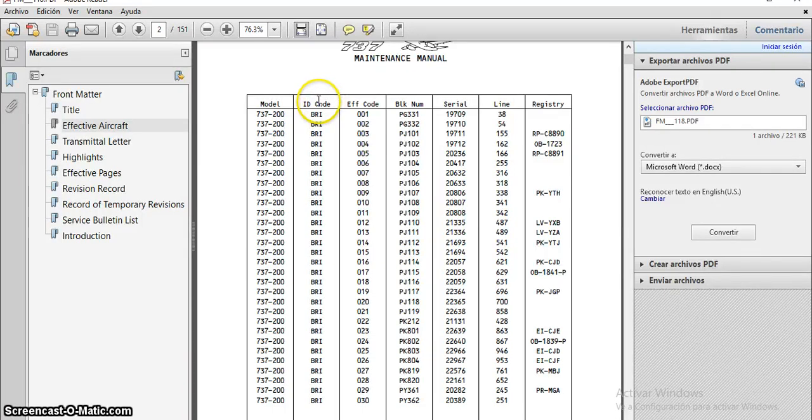Well, the next part of the laboratory is based on the steps and procedures to carry out the maintenance process for different components of aircraft. When a component must be changed, we use the manual called IPC. In the IPC manual we have the components and their part numbers, and the effectivity code of the airplane.